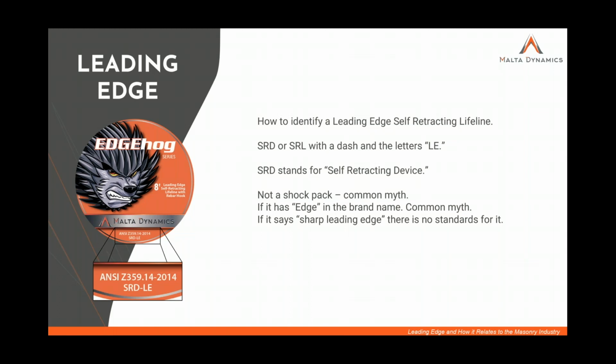Some common myths is a shock pack. It used to be some manufacturers would put a shock pack on a retractable and claim it was for leading edge. That was a big selling point for years. Not the case. There's specific testing for leading edge retractables, and if you pass those tests, you put LE on the retractable. If it has edge in the brand name, another common myth.